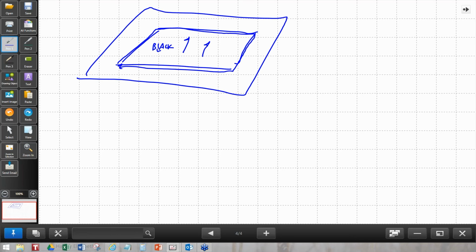There are other such things that sometimes are done. Sometimes people will actually have a place where there's a pressure on the bottom and there's a pressure on the top, and for some reason they need to be sealed. There's a different gas on the bottom than on the top, and they're trying to measure some pressure or do something. So sometimes they will actually use solder mask to seal those things. It can't take very much pressure, and it's not designed to do that, so I certainly can't recommend it, but I have seen it done. So again, watch for the specialized purposes, and if any of them come up, you're going to need to make sure that the solder mask you choose can handle that.